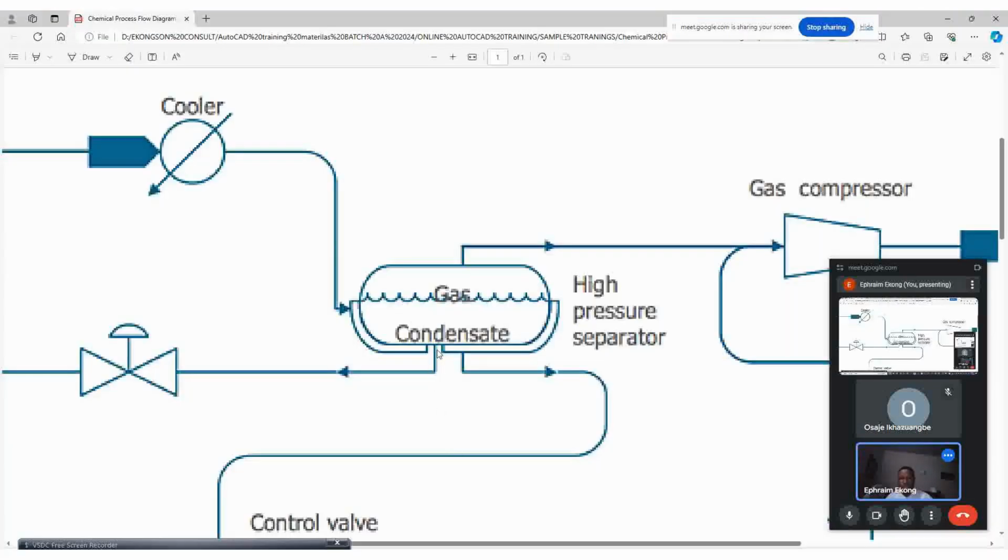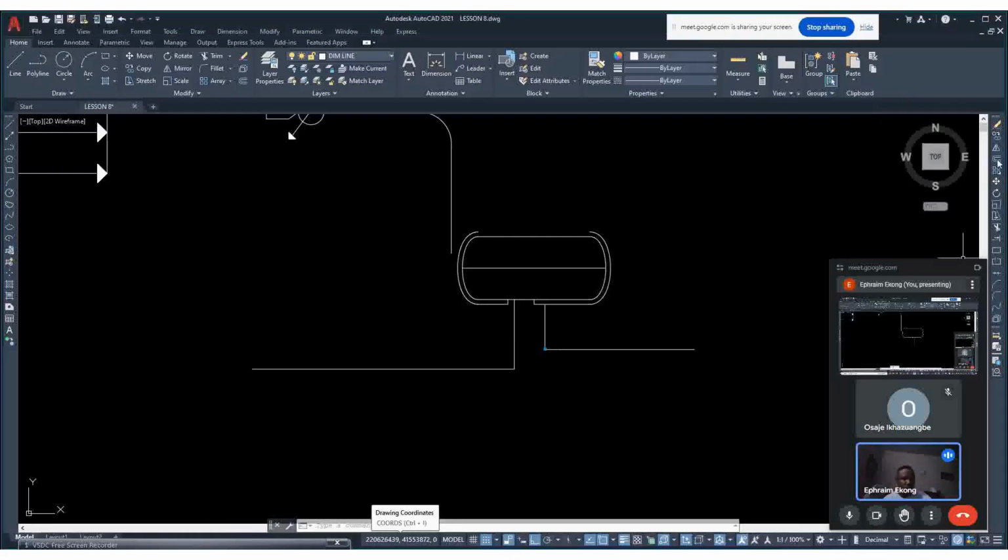We want to achieve this part. Okay, so the distance from here to here is what? We could use 1000. So we offset 1000. Click on offset and type 1000. Press enter. You offset this line downward. Okay. So we go to trim and press enter. Click at this line. Okay, then highlight and erase. You highlight and erase.